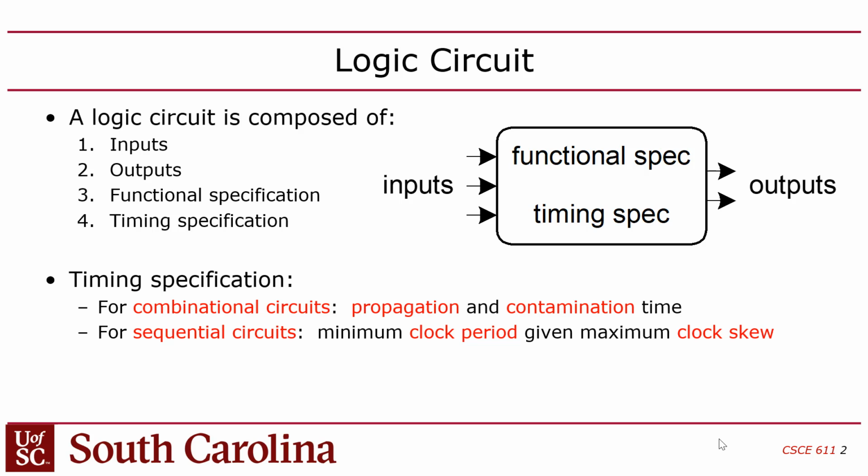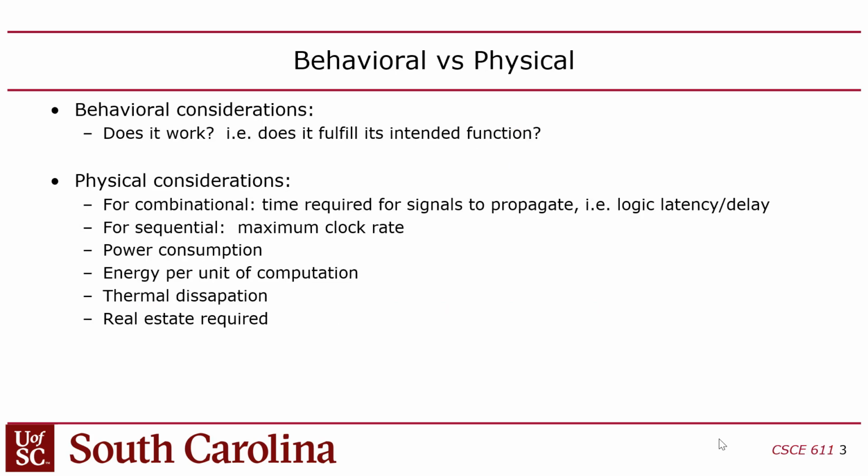And for a sequential logic circuit, the timing spec is the minimum clock period, or the reciprocal of that, the maximum clock rate. Okay, and that's often assuming certain factors like a maximum clock skew or environmental conditions like temperature. All right, and I'll talk more about that too.